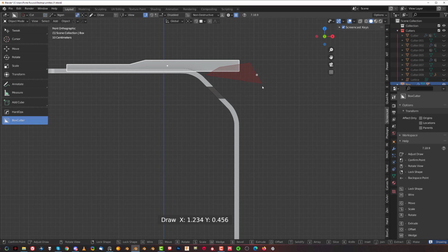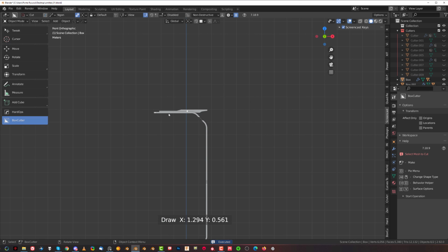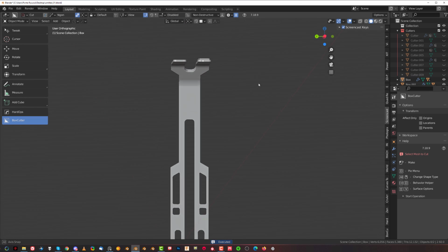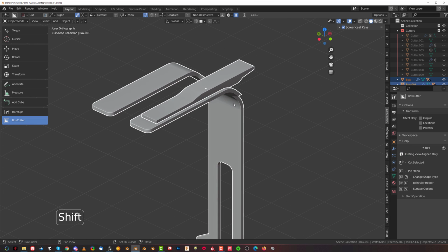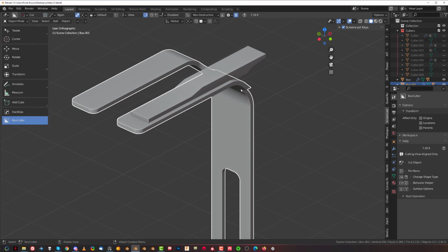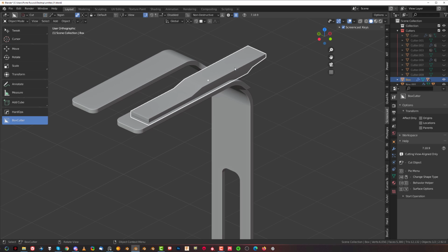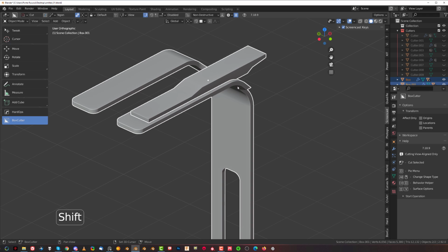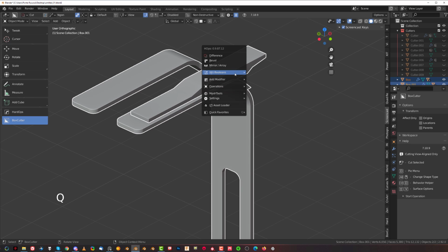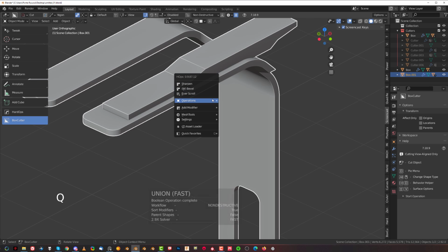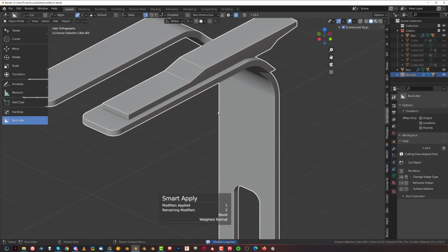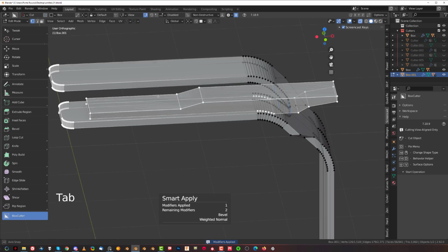And we're gonna do something like this. Hold Control and create this kind of shape. So it's gonna be really light and sort of like a head of a bird or something. So now let's select these two and Q. Now the order of selection is important. This one runs bevels. You don't wanna use a boolean that has bevels. So select this one first, Shift select this one, then Q and booleans union, right? Okay, and then operations multiply, and you're done.